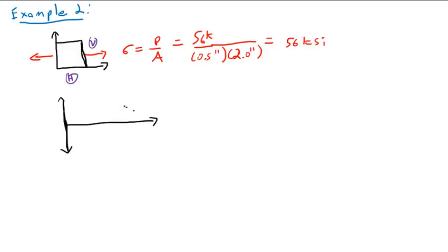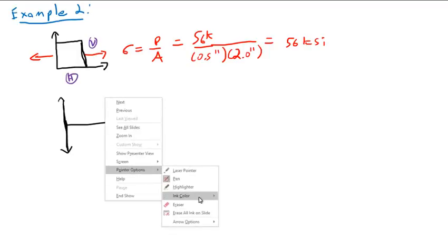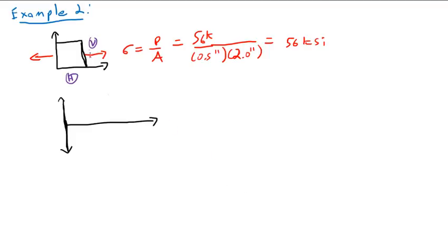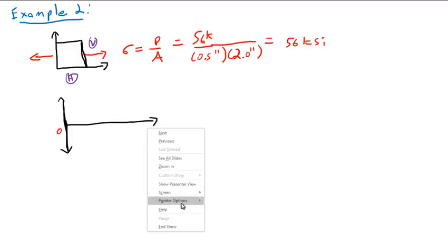So we have this here because we are shown that there is only an x normal stress here. There's only a sigma x, not a sigma y. So our lower point is just 0. Previously we started with two arbitrary points that were not the principal stresses, and we solved for the principal stresses. Here I'm given the principal stresses, and I want to back solve for the average.